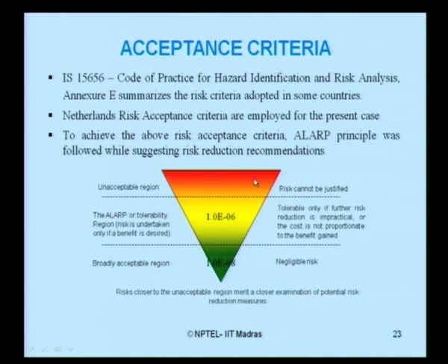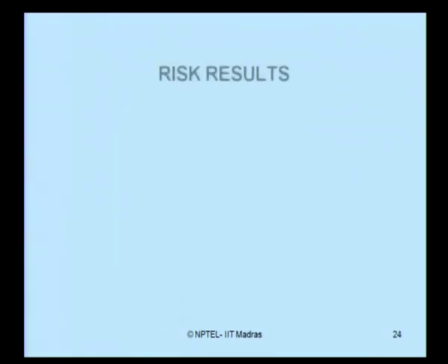You have calculated risk for every event on the pipeline segment, every event on the tank segment for different scenarios. Now, pick up only those numbers and see where they fit in the ALARP triangle. I have done that.